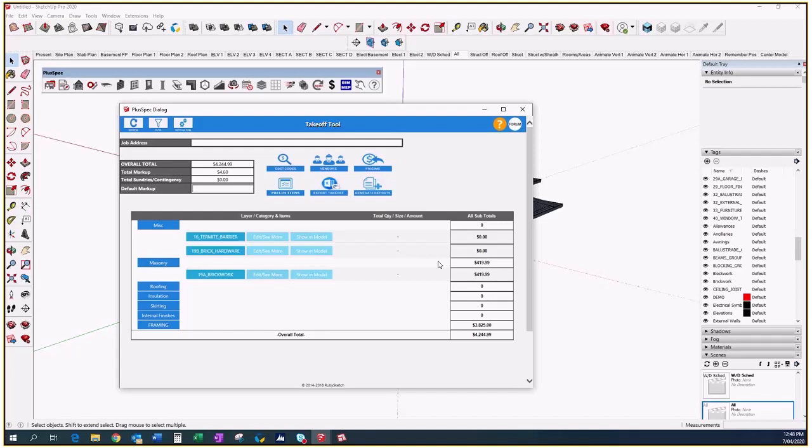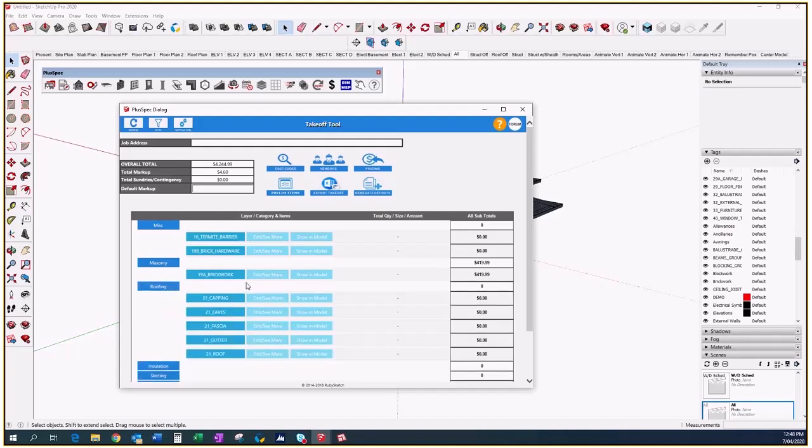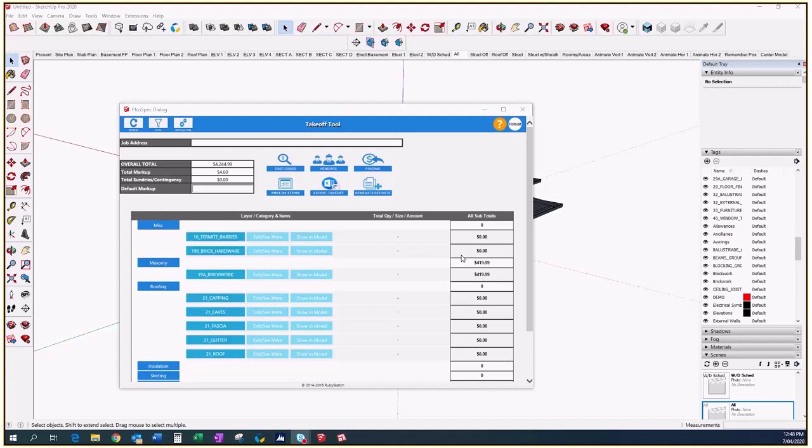I can also manually put them in there, and I can understand square meters and linear meters of every single product that I've drawn with. Obviously, as a builder, this is really important. It means that not only can you model, look for clash detection and create these virtual design construction models, but when you are doing that, you're also creating your cost estimate, your takeoff, or your bill of materials, whatever you want to call it. So you're really doing two things at once.